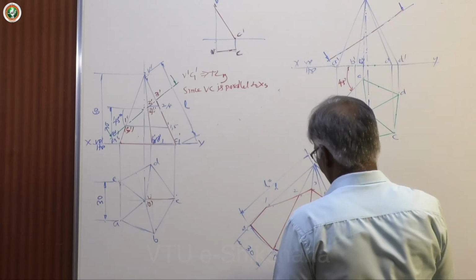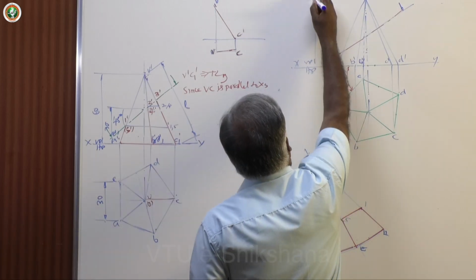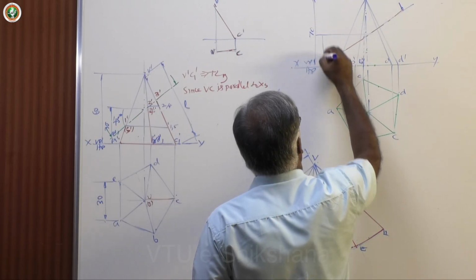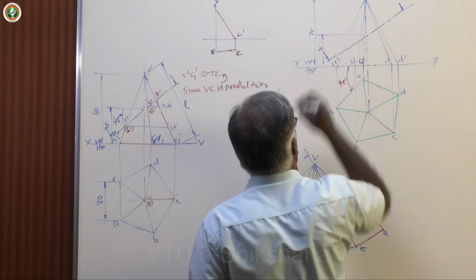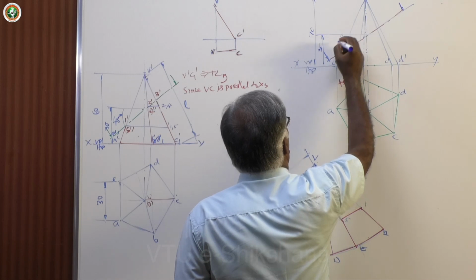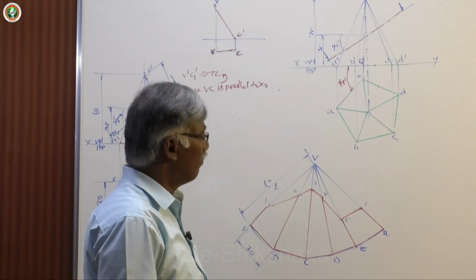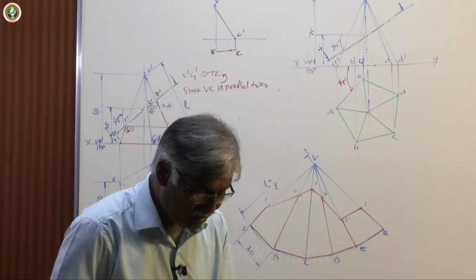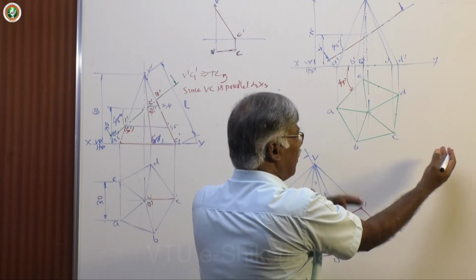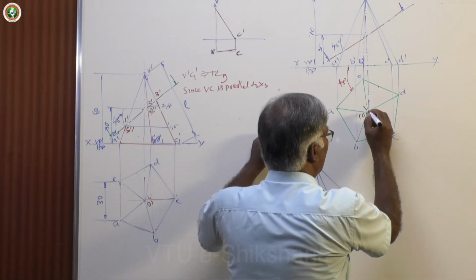You now identify, okay, axis height, or otherwise how much they give you can take accordingly. So, this is 35 then, bisecting the axis, 45 degree or whatever the angle they give. Basically, we have to find out the true length here, because none of the lines are parallel. Now normally we take to the right side either VD you take or VC. Let me take VC only.